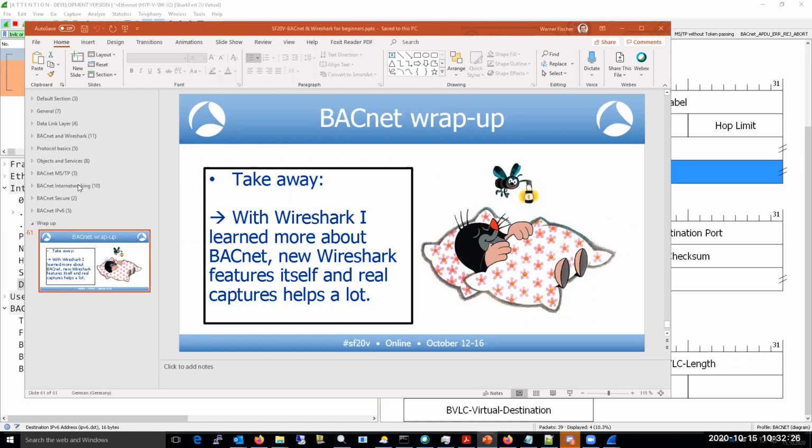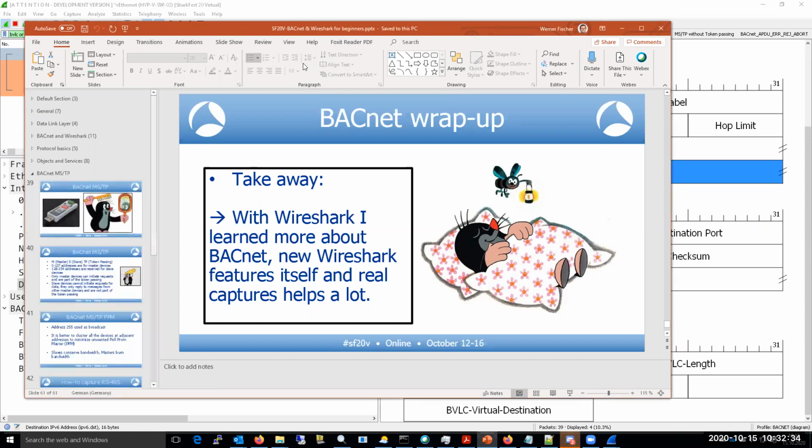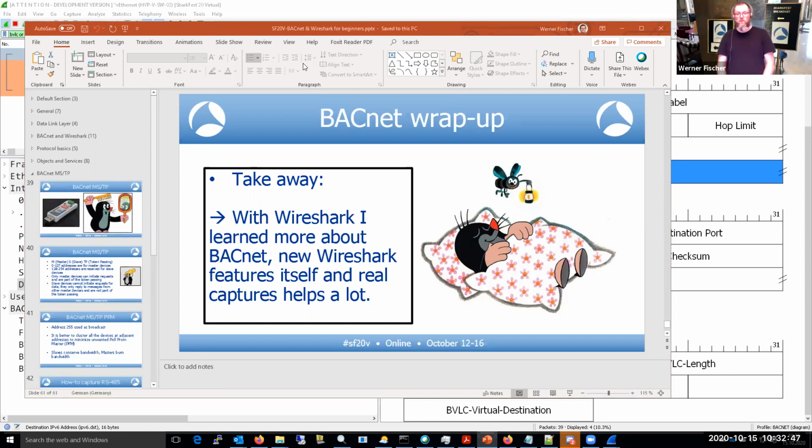Yes. We do have one question asking, is the BACnet protocol very widely used? It certainly is around building control. It's leaked out into one or two other places, but it is the de facto standard in building control, heating, ventilation, and air conditioning. Yes, it's used very often.